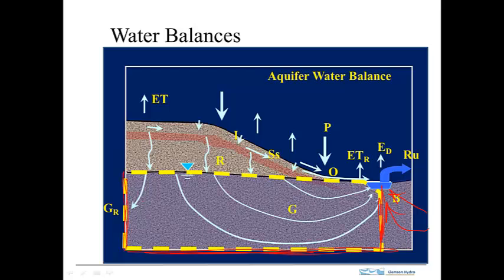So this would be an outflow. Recharge is inflow. This is groundwater flowing out of the control volume. Recharge coming in, and we have base flow coming out, the groundwater that discharges to the stream. So that's an outflow.